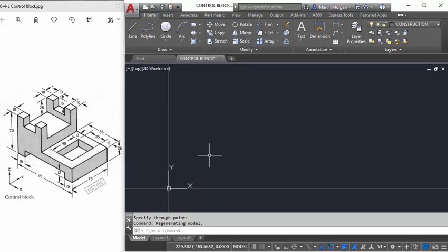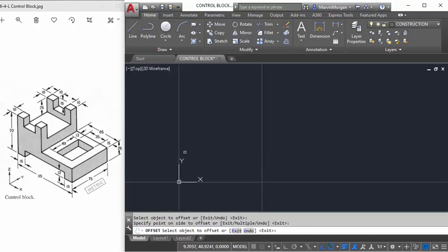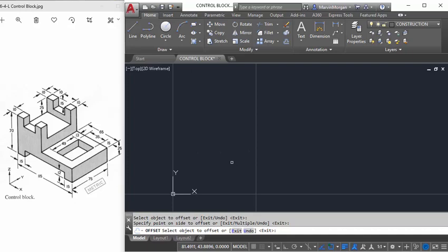At this time, we're going to do a series of offsets to identify all the widths in the front view of this image. So, going to our offset command, our first width is the total distance, which is 115. So we type it in, 115. Click this line, click to the right. So therefore is our max width. I'm going to press enter to end the command.